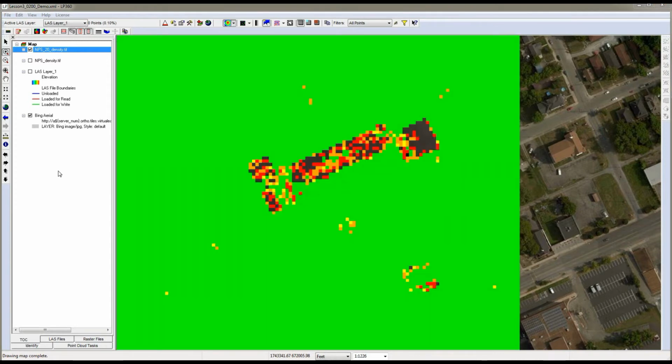In a case like this, where we have a localized void that can be tied to a physical explanation, reflying the data again is not likely to produce a different result. So this would be allowable, however it would be documented in the QA/QC report.